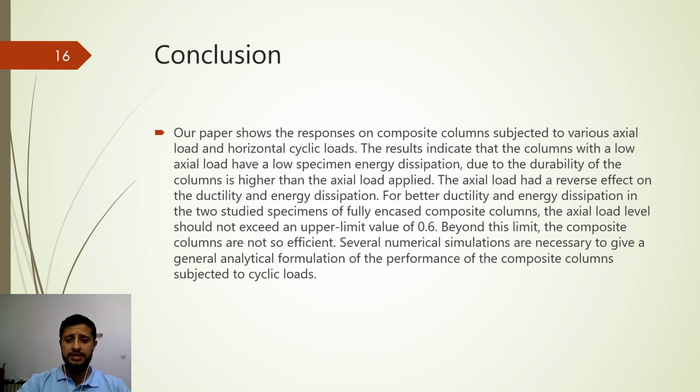For better ductility and energy dissipation in the two studied specimens of fully encased composite columns, the axial load level should not exceed an upper limit value of 0.6. Beyond this limit, the composite columns are not so efficient. Several numerical simulations are necessary to give a general analytical formulation of the performance of composite columns subjected to cyclic loads. Thank you for your attention.